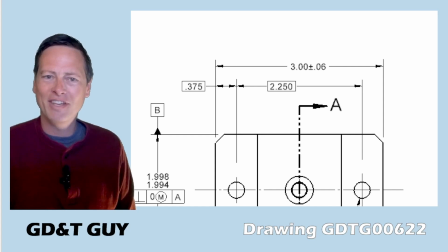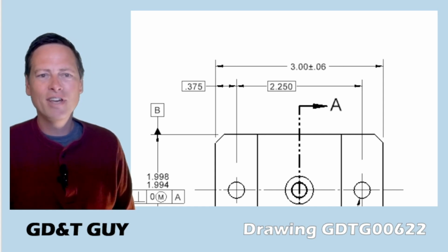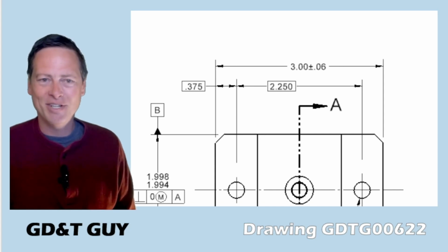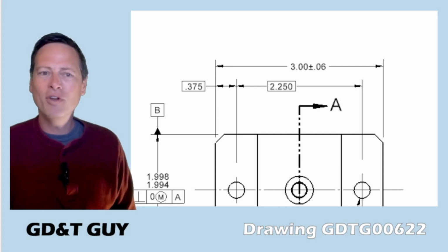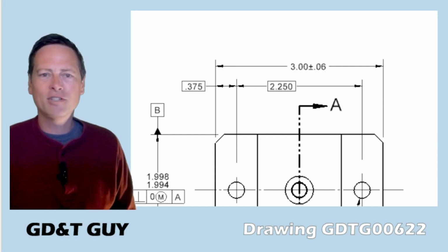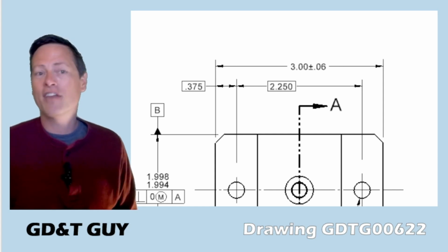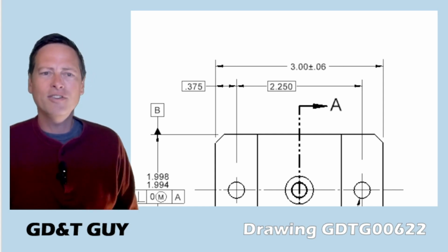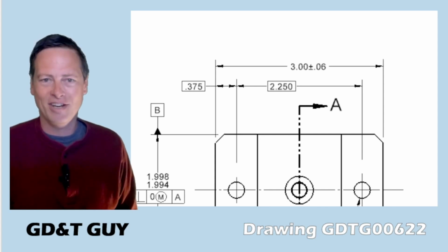And there's another thing here, which is that this 3 inches plus or minus 60 thousandths is a mere size dimension, subject to rule number 1 if you want to think that out, and with no clear origin. This plus or minus tolerance does not really locate the rightmost end in the datum reference frame. It's better thought of as a feature of size width feature, together with the leftmost end. You could do this measurement without the gauge, in other words.